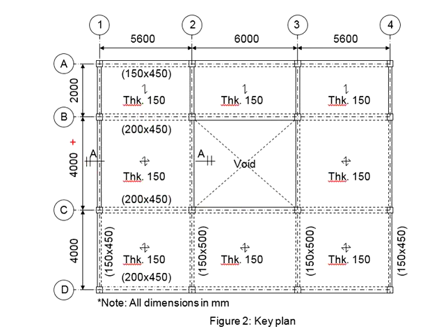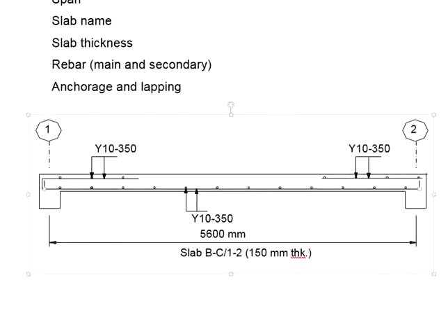Since the question is asking about section AA here, you will see the bottom layers here and the top layers here. When you view from this side, that's why you will see the longitudinal rebar at the bottom. If you cut the section here and view from the other side, then the condition is reversed. It will end up being something like this.